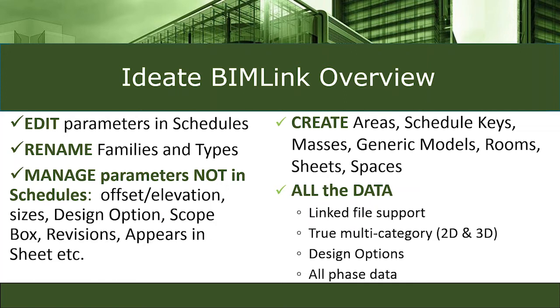So we're going to be able to look at linked files. Now, when it comes to modification, you're only able to modify elements in your main file, because that's sort of like a Revit key, in the sense that you can only modify things within your master model. However, if you wanted to, as an example, do a quality control link of all of the worksets that are used across 15 linked models, you could certainly do that. Or maybe you'd like to look at all of the families that are used or door types. So when it comes to quality control, that linked file support is really important.